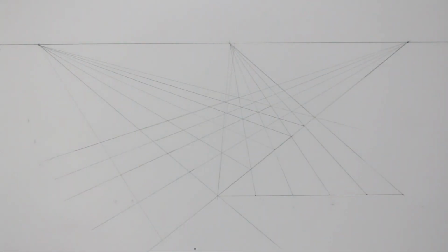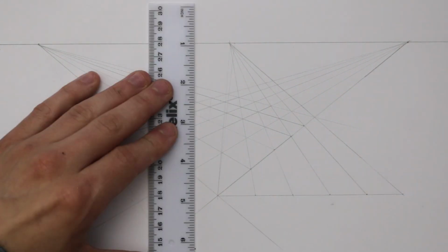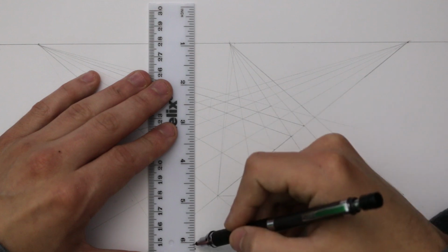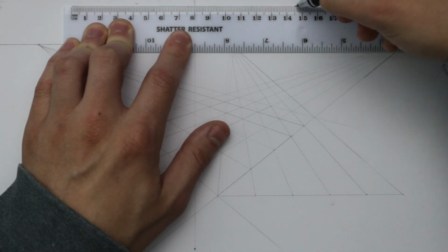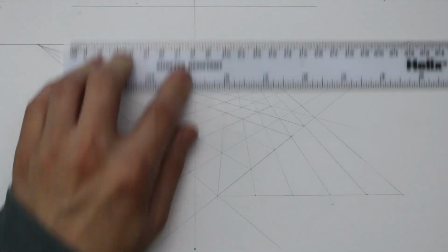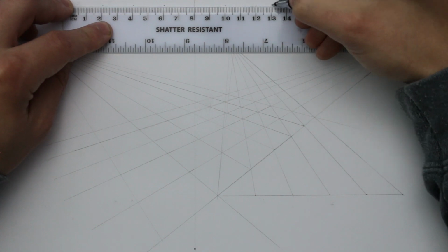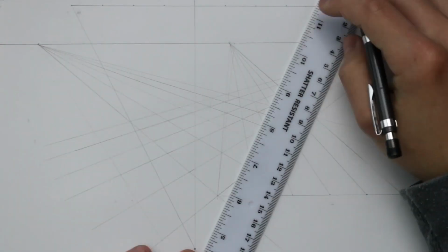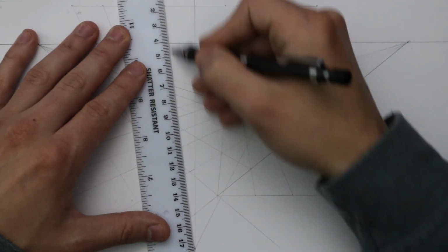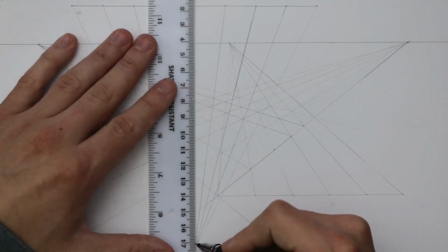So now we have to add another series of grid lines over this which are directed to that third vanishing point. I'm going to start by drawing a vertical line at that vanishing point and a horizontal line that is above and parallel to the horizon line, which I can divide up into sections. I then take some lines from each of these points to that vanishing point below. This gives me all of the necessary grid lines to draw in 3 points perspective.